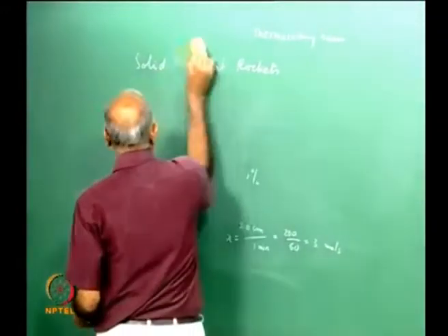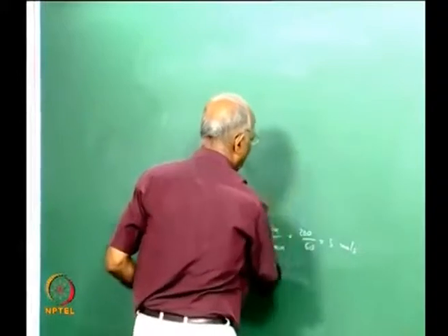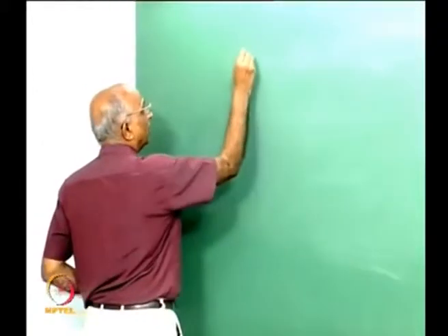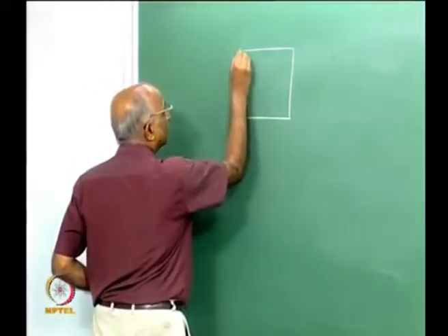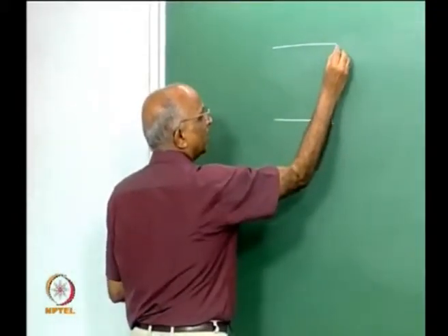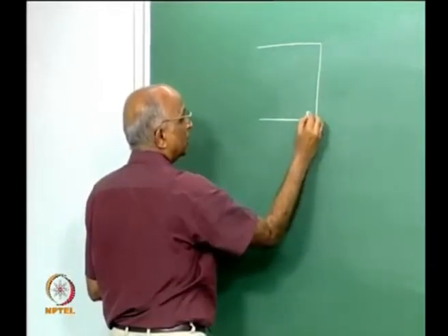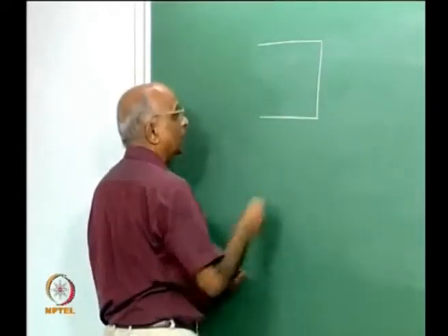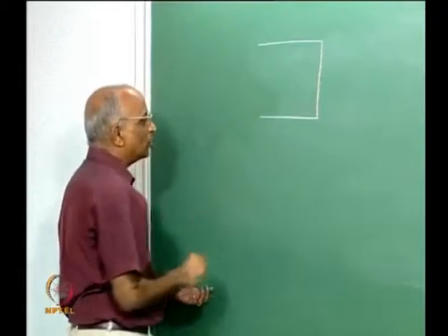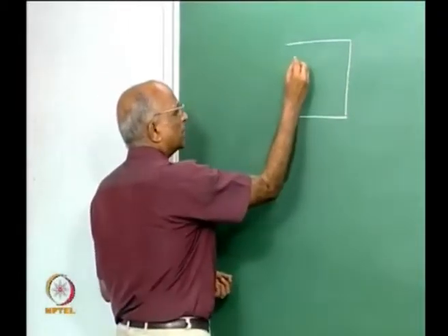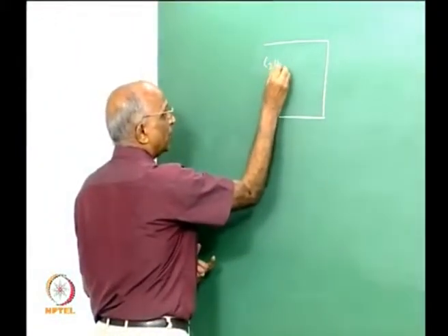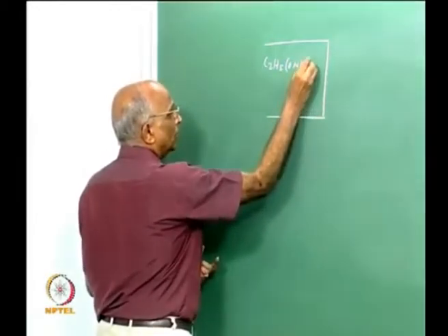We will try to get into some details, we will try to see whether we can make some sense of what our composition was. Let us say I have a double base propellant over here, and just the same way I ignited the sparkler, I put a fire or a heat source over here, and start igniting it. In other words, I start igniting this particular surface with a heat source. What was the composition of double base? We told that it consists of maybe nitroglycerine, which is C3H5(ONO2)3.